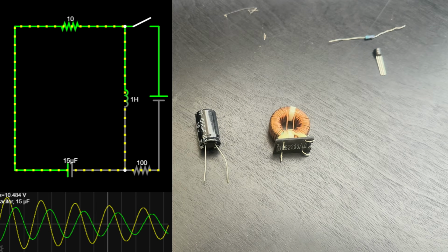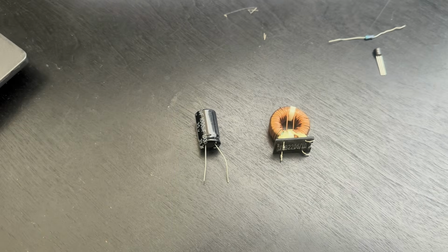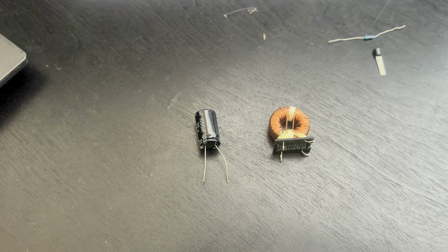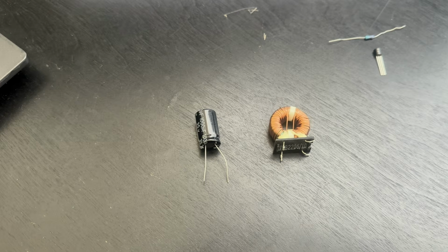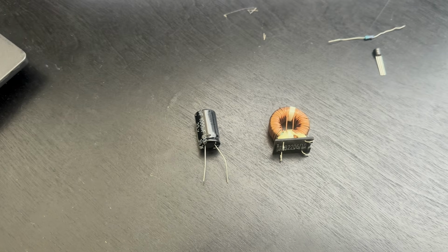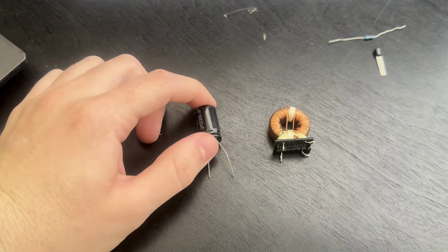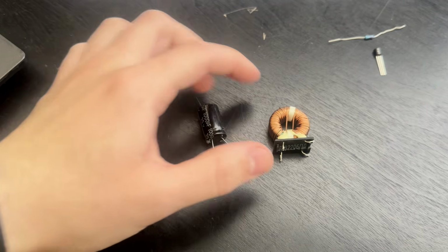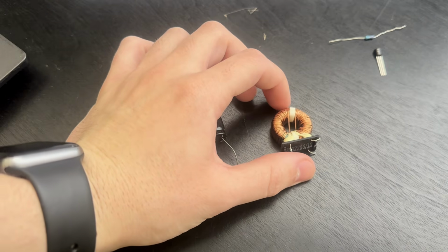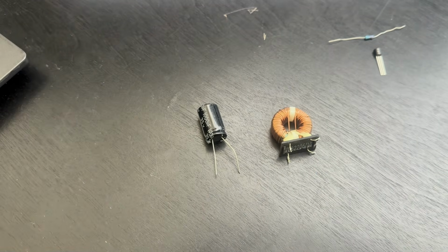But essentially, if we look at a DC electrical circuit, which is what most electronic projects are going to be based off of, DC meaning direct current. So it's like battery operated stuff, not the stuff out of the wall outlets, which I assume nobody's going to use for a basic electrical project. Capacitors act like open circuits, and inductors act like a short circuit. Essentially when time equals infinity, so in the long run.